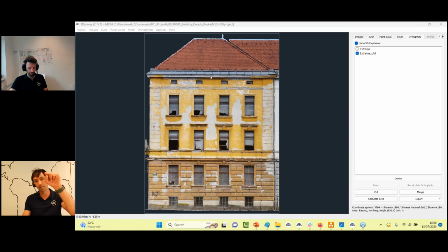So just click import. You first need to import the Gauss-Krüger points in 3Dsurvey as CAD points, then the same points as UTM as CAD points, so that you have two layers, and follow Matthias's workflow, and you will transform those coordinates. Check it out and let us know if you need some additional help. Francisca, yes, there's a tutorial already online on our YouTube channel that explains the workflow. I also did it today on the exact same data set, so you can also watch it there. It's a bit more edited and less raw, I guess.